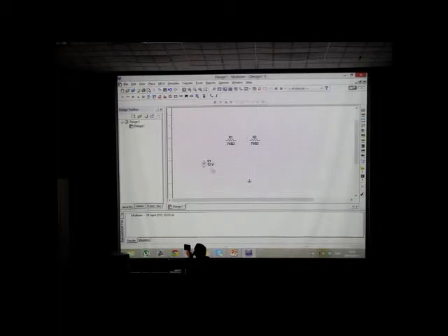So to connect, bring the mouse pointer to just the tip of the other component. Click here and it starts. If you want an anchor here, you can just click and it will stick there. So anywhere you move, it will just be there. You just click here and it will be fixed to that point. Now from here you can bring to this. So these two are now connected. This is just connected, nothing like PSpice, where sometimes they don't connect.